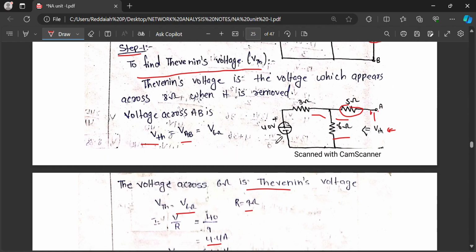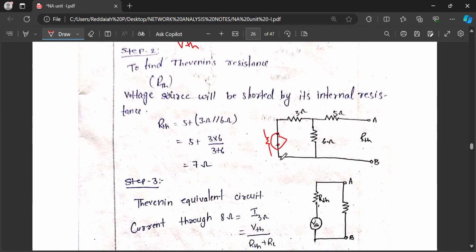In this circuit, we have a voltage source, it should be short circuited, because in short circuit voltage is 0. We are deactivating the voltage source and current source. Deactivate means voltage becomes 0. Current source means if you open it, suppose in place of the voltage source a current source is there. How to replace the current source? Current I equal to 10 amps, assume that. 10 amps we have to make 0. We have to make it open circuit.